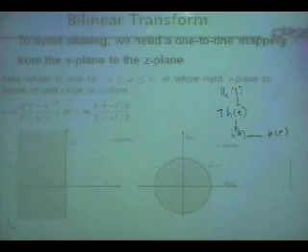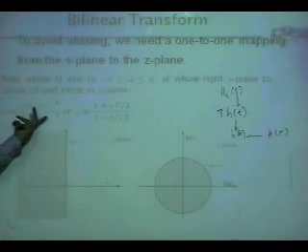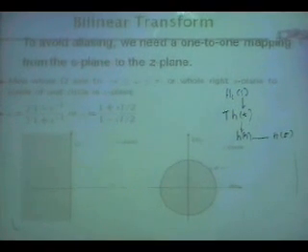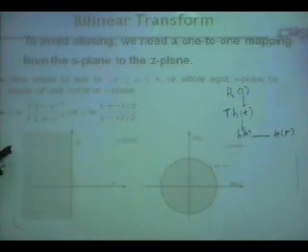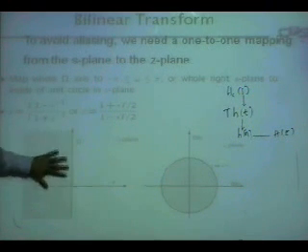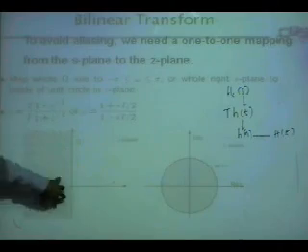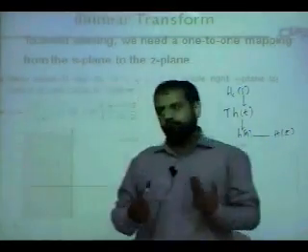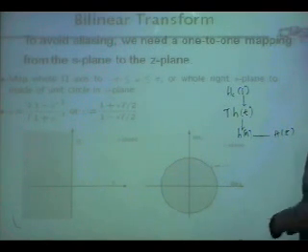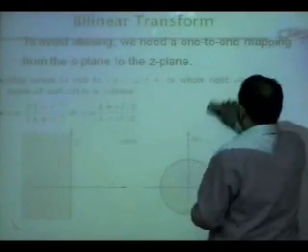And we only need to prove that this expression means what I showed you in terms of j omega and small omega. We'll shortly find that out. And also we need to make sure that this expression will ensure that this left hand side of the S plane is mapped inside the unit circle, so that stability there guarantees stability. So these are the two things which you need to make sure still happen. So how to prove this?